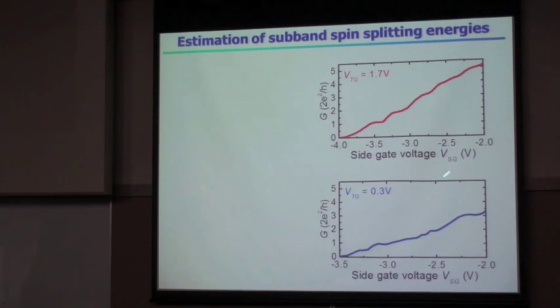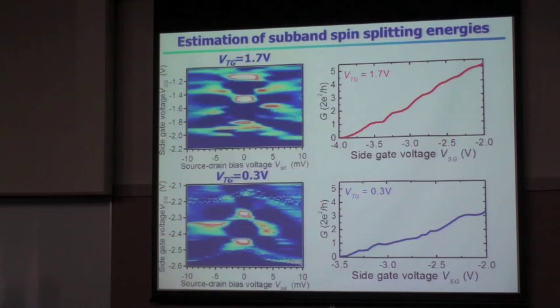And in these top gate bias conditions, we measure the transconductance, because transconductance can give the energy levels in the QPC structure. And here is a result. And this dark point corresponds to this plateau region. So for example, this region is the 0.5 plateau, and this region corresponds to the 1 plateau. And these red points correspond to the characteristic bias voltage.